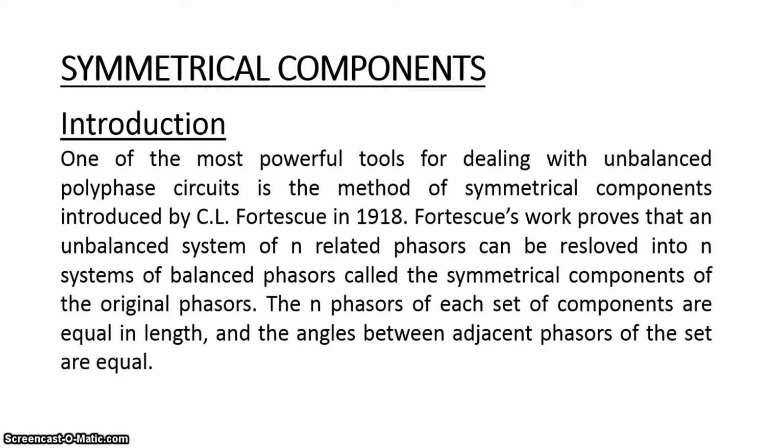Alternatively, there is a more convenient and elegant method of analyzing unbalanced systems. This approach was developed by Dr. Charles L. Fortescue. This is called the method of symmetrical components. It is a mathematical tool for understanding and analyzing any unbalanced polyphase system.